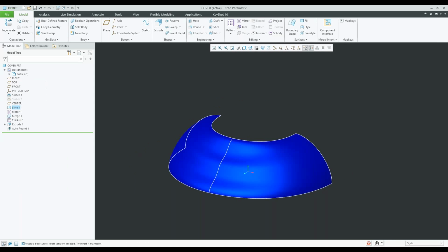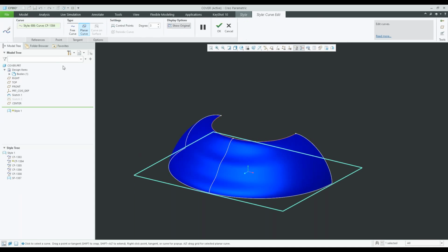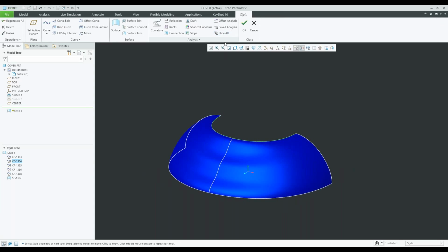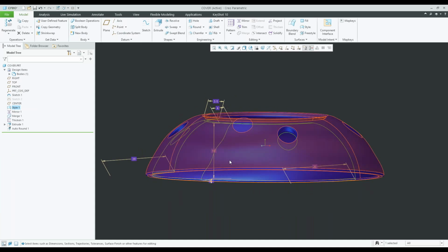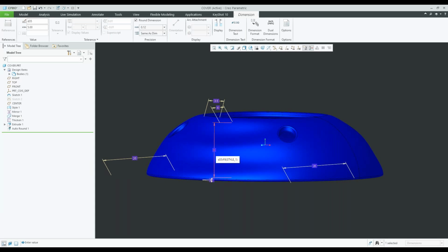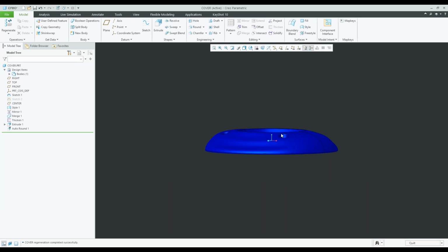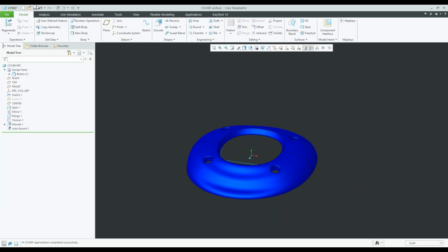One thing I should probably add that I didn't is, if I go into this top curve that we copied and offset, I can actually add that as well. So I can go to offset, add that parameter, click OK, click OK, go to the style feature, edit dimension, and now here's an offset dimension. If I want to bring this down a bit, halfway, I can change it from 10 to 5, click enter, regenerate, right? And now that's obviously a lot shorter than it was. Undo that.